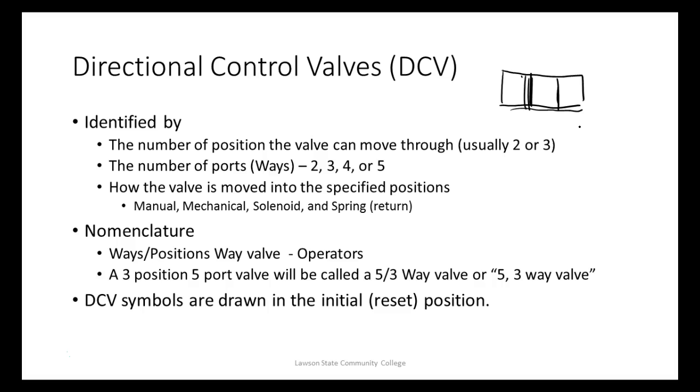The ports, it's going to have 2, at least 2, right? It's got to have an inlet and an outlet port. It could have 3, 4, or even 5. The only way you're going to see a 5-port valve is if it's a 3-way valve and they have 2 exhausts.